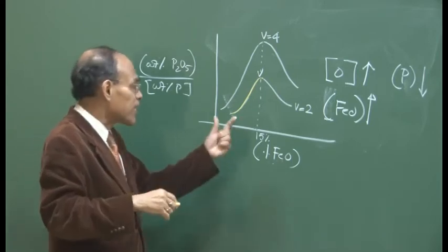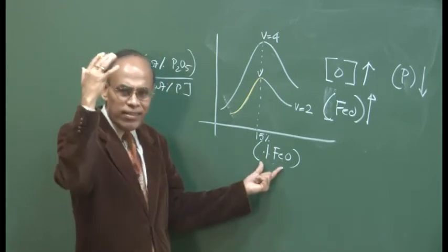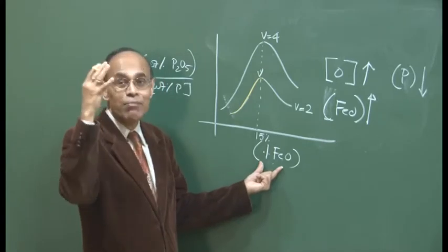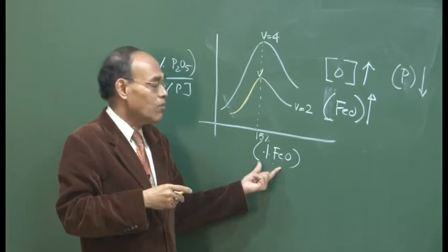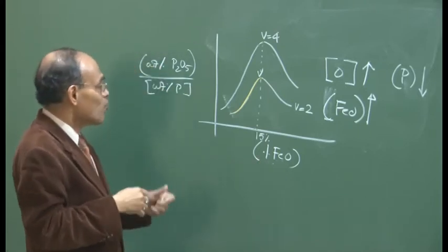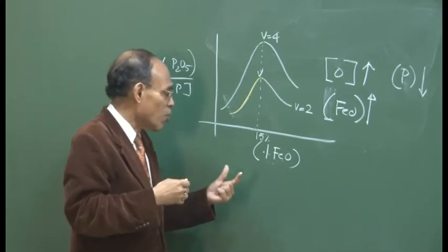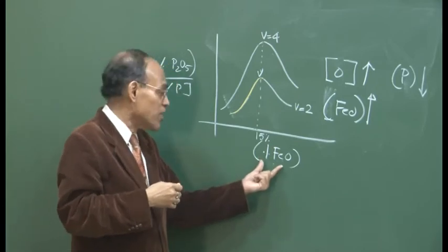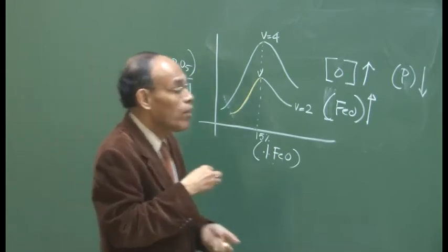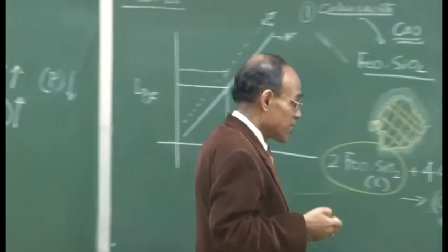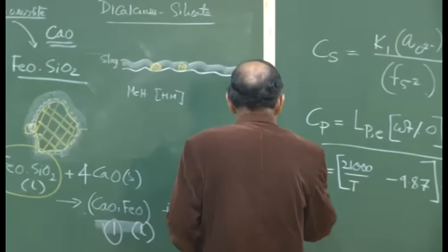So hitting the correct FeO content in the slag, the correct carbon composition, and the correct bath temperature is not an easy task, and you cannot just do it by experiments or trials. You have to have modern machineries as well as sensors to guide you, so that you can arrive at the endpoint precisely.